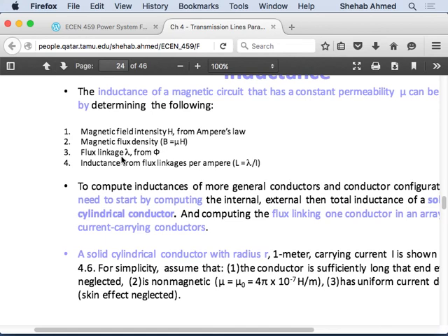There's magnetic field internal to the conductor, magnetic field external to the conductor. If it's internal to the conductor, it's linking a smaller area of the conductor, right? If it's external to the conductor, it's linking the full conductor, right? So in that case, there's no difference between flux and flux linkage. Or flux linkage is equal to the flux that is outside the conductor.